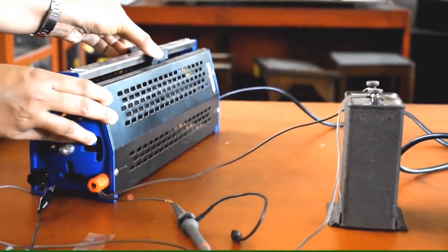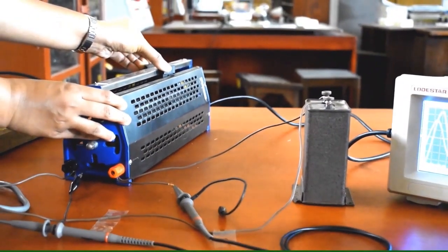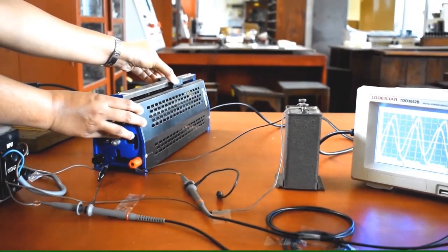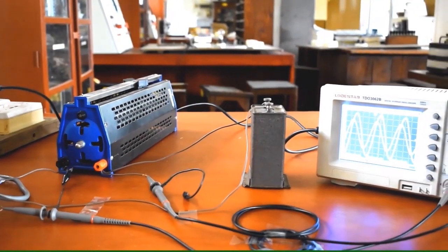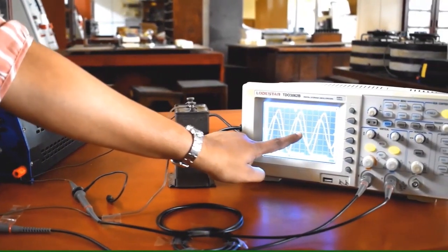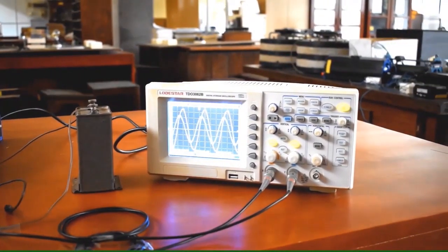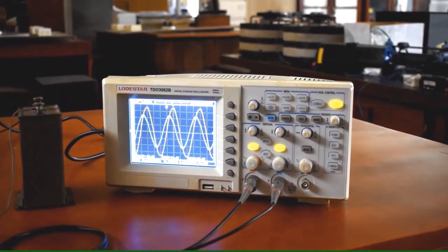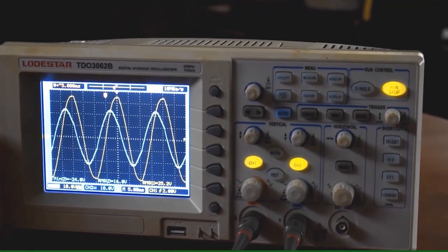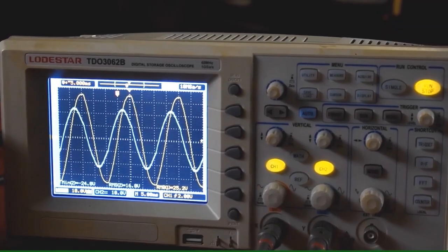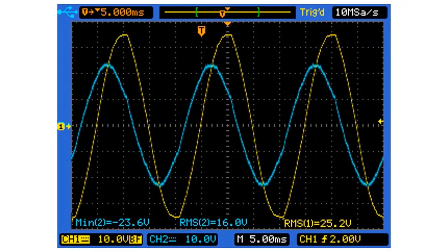Change the resistance so that you can sketch the phase shift clearly and easily. Sketch the waveform in the same grid with the supply voltage. Name the axes and waveforms clearly. Count the difference between the two waveforms using smaller divisions. Use this information to calculate the phase shift.